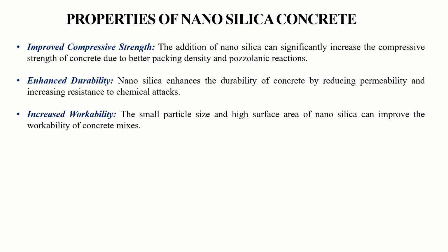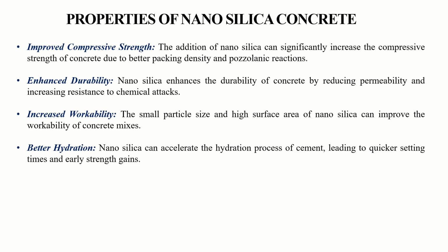And talking about workability, up to some extent the workability can increase with increase in nanoparticle addition, but at a later stage, due to the more fine particles, nanosilica particles being more fine in nature, you may get a reduced workability. At that time we can take the help of a super plasticizer. Then better hydration: one has to remember that the finer the binder, the more the hydration.